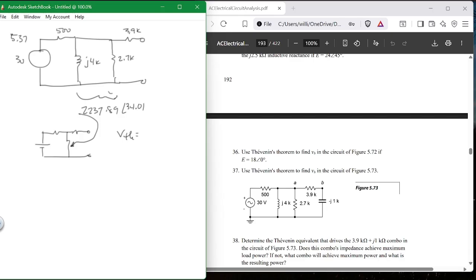So you're looking for, is that resistor there or is it not there? If it's not there, good. If it is there, you don't count it for V Thevenin, you count it for R Thevenin. Does this make sense? Because this is how this is done. This is how Thevenization works. Good, bad, or indifferent, this is it.